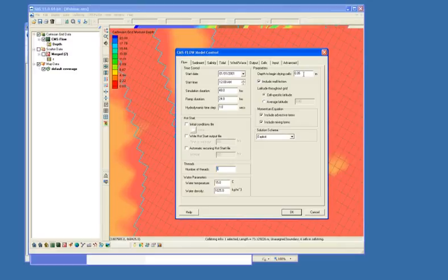As the water level decreases, when a cell only has 0.05 meters in this case of water left, then internally CMS would declare that cell as dry. It'd be outside of the computational domain for a period of time until the conditions existed when it would be wet again. At that point, CMS would consider it wet, and it would enter back into all the computations.